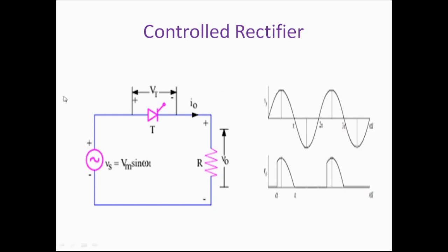But here we will talk more about this device later. Right now remember why I am saying this is a controlled rectifier. This SCR will turn on only if you apply a gate pulse to the gate, or a gate voltage, or if you inject a gate current.